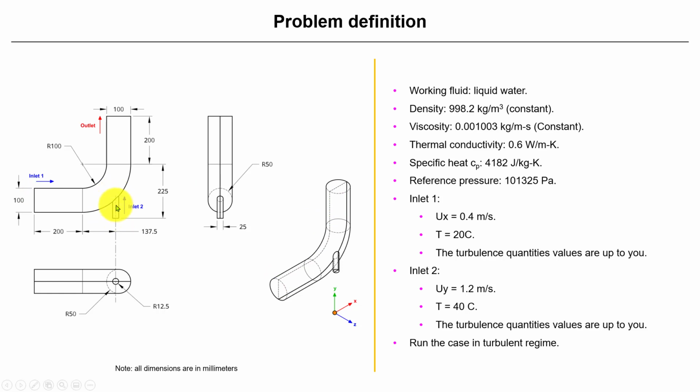Then here also we're going to create something similar, so you can use extrude or sweep. So you create a circle somewhere here, you have all your dimensions, and then do the extrusion, create the boolean, and voila, you are ready. So you are going to get the whole pipe. Then probably we can use some other tools to split this profile in two and use symmetry. We have all the conditions here, so it's the same as the previous case, as you see.